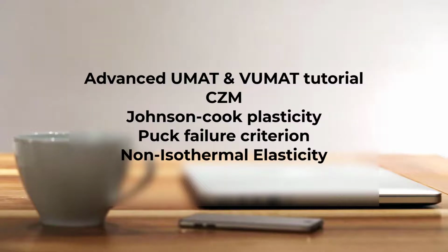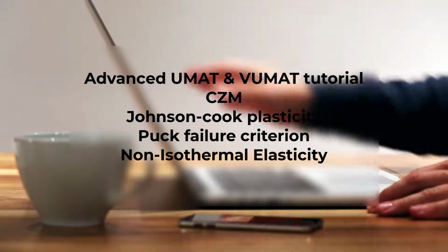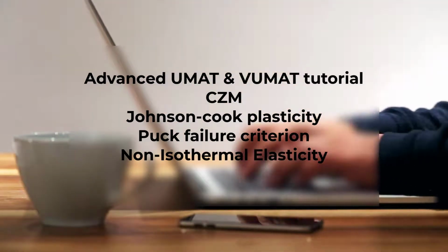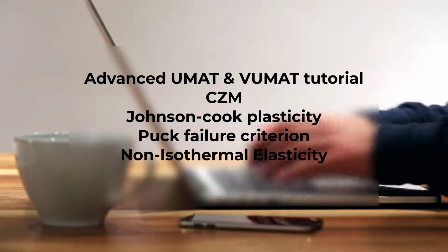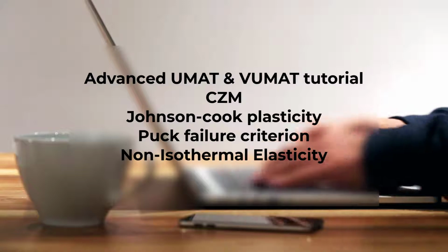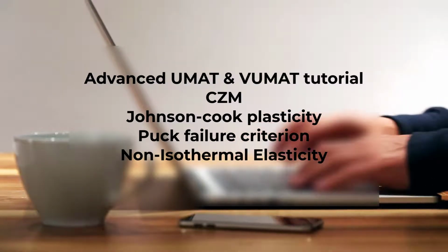It's time to level up your skills in UMAT and VUMAT subroutines. In this video, we'll show you how to use these subroutines in non-isothermal elasticity, damage initiation, and progressive damage based on Puck failure criterion of composite material, and other things, all with UMAT and VUMAT subroutines. So, be with us till the end.